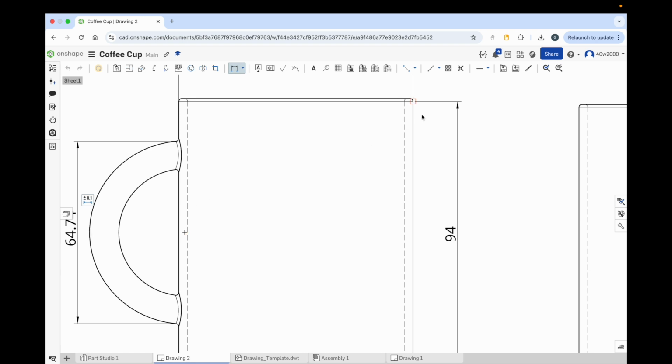To do that, if you look at the top of the screen, if you go to the horizontal, vertical, oh no, it's not that tool, it's further to the left, there we go, the line tool, and then click on sketch point, click that, and you'll see that the target kind of snaps to the line, you get that little red icon. We're going to click on that center point and it changed to a square there, so click that, and we'll do the same on the opposite side of the handle. So we've got these 2 points that we can use as anchors.